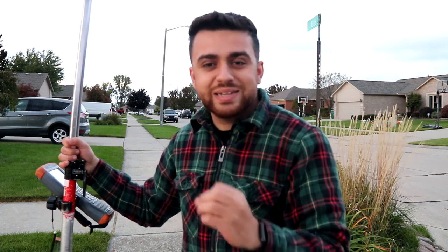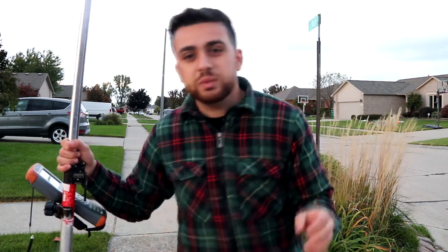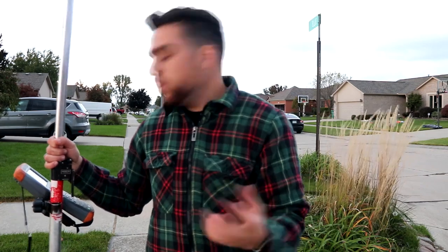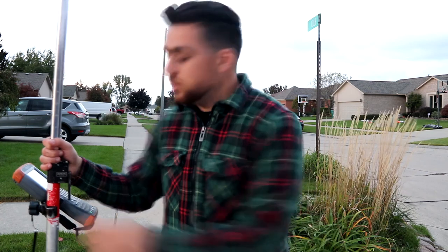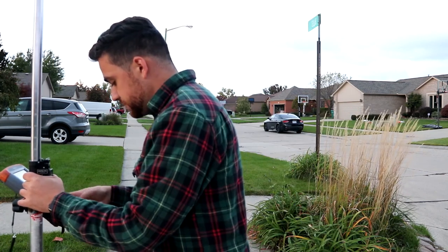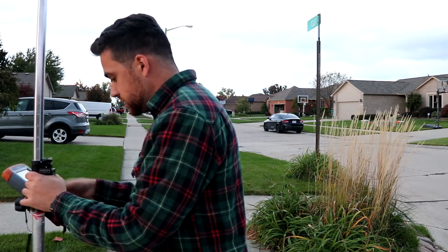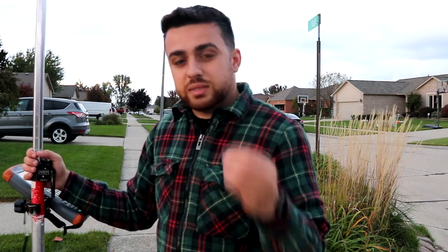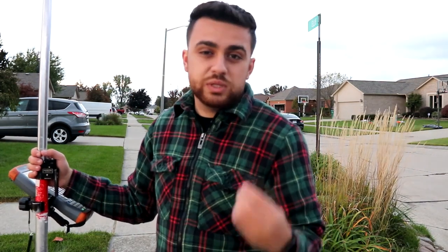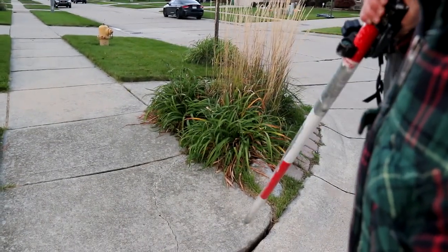My coding is going to be curb 1 space concrete 2 minus 7. This could also be E or end or whatever your software is programmed to end lines. Mine just happens to be minus 7. So this will be curb 1 space concrete 2 minus 7. Once you've done a minus 7, you can now reuse this code again. So I'm gonna go ahead and use it right over here to start concrete again.